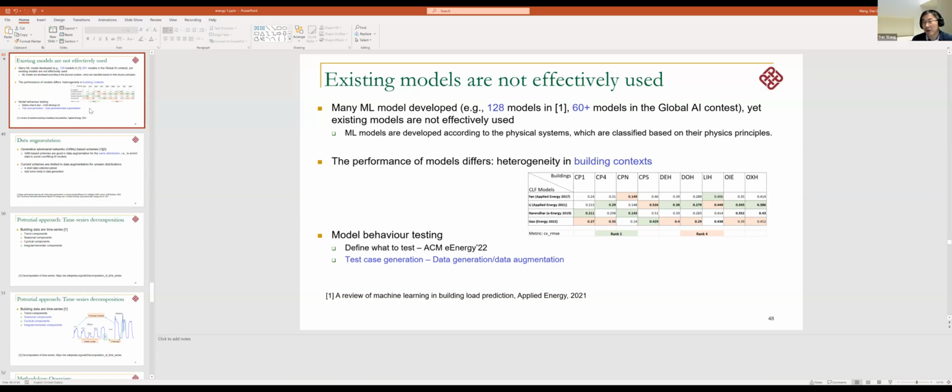No, we haven't touched RL because RL is more difficult. It's more difficult to get the ground truth. From my understanding, when we talk with building operators, they are more skeptical because they lose more control with RL. With MPC, for our chiller control, they still have certain rules for safety, an upper bound and lower bound. Then your data-driven approach can only work in a range. So for MPC, it's easier for them to add these rules.